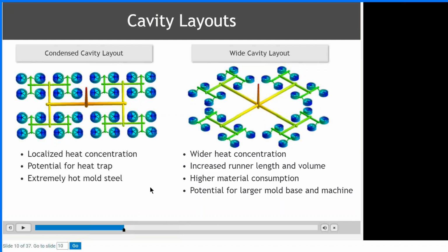So what I'm trying to say here is, please understand how the cavities are laid out, understand where the heat is inside the mold, because the heat will drive the cooling of the material and therefore shrinkage and warpage, because that's really what we're talking about here: shrinkage and warpage. Create a heat map inside of your mold, A side, B side, measure the temperature of each cavity, map it down on a piece of paper to see how equal it is in the tool. Maybe you discover something.